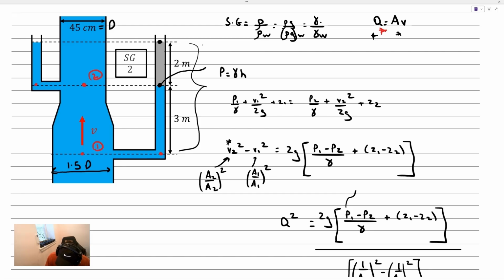The pressure at that point is equal to the density of that fluid, which is twice as dense as water, multiplied by the depth that we went into that fluid. So the pressure right there is 4 gamma. I'm going to descend by 3 more gamma to end up at this point, which is equal to the pressure at point 1 since they're at the same elevation. That's 4 plus 3, which is 7 gamma.